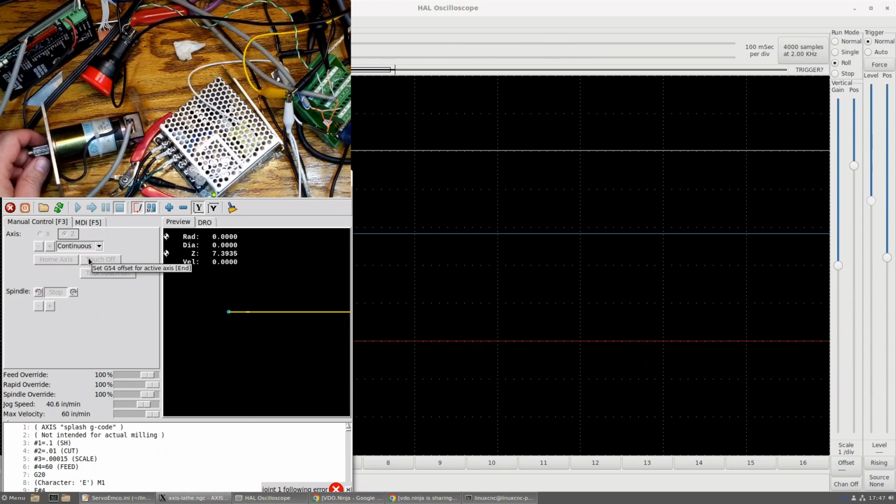Steppers work fine, but a servo that has feedback to the control, so the control can keep track of position, is so nice. On our big machines at the shop, I can turn the machine, the actual Linux CNC off, like turn off the drives and everything, and Linux CNC still keeps position. So I can come back a little bit later, turn the hydraulic units back on, turn the drives back on, and it knows exactly where it was, and I can take off where I left off.